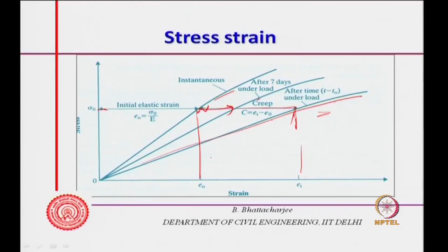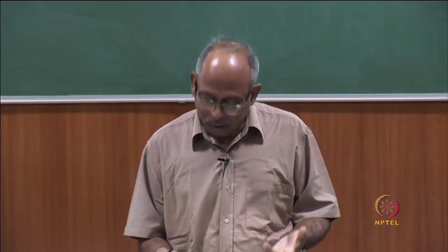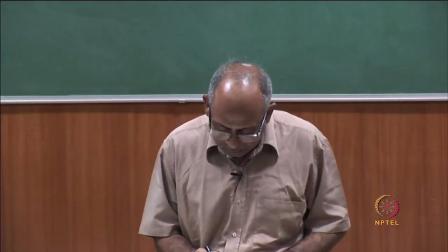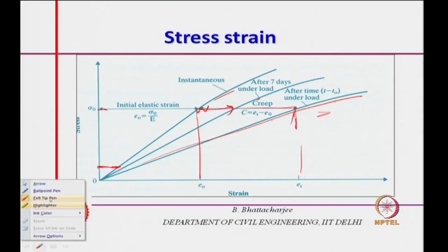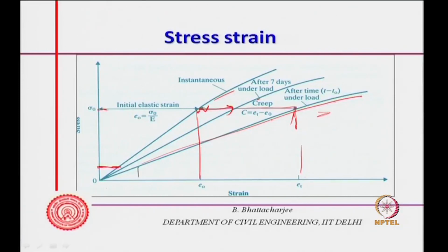In other words, the effective modulus has also changed. So, if I am considering at some later time, for example, if this is my stress level, the instantaneous strain will be this much, and this will be the creep. So, instantaneous is this much, and this will be the creep.